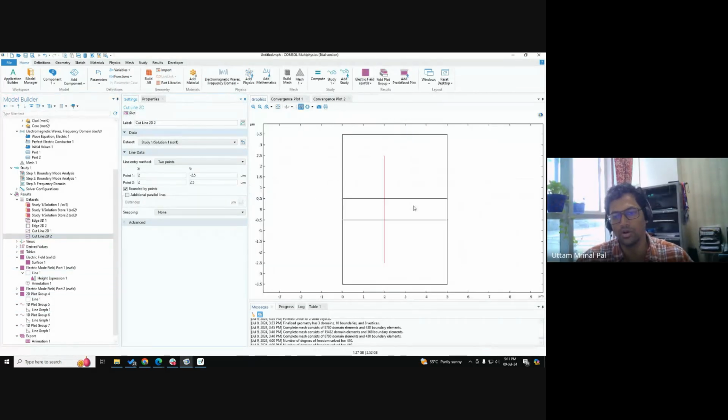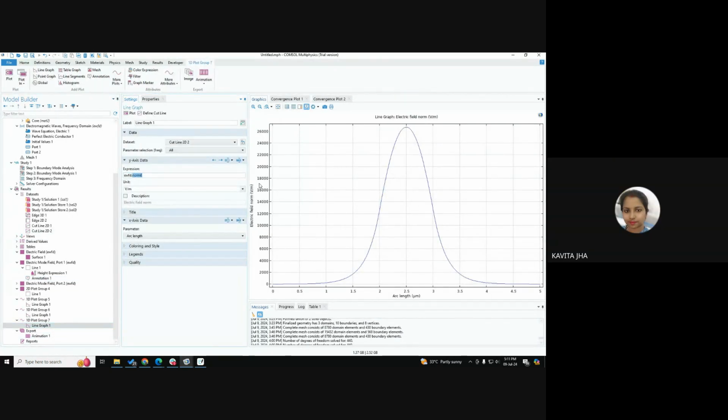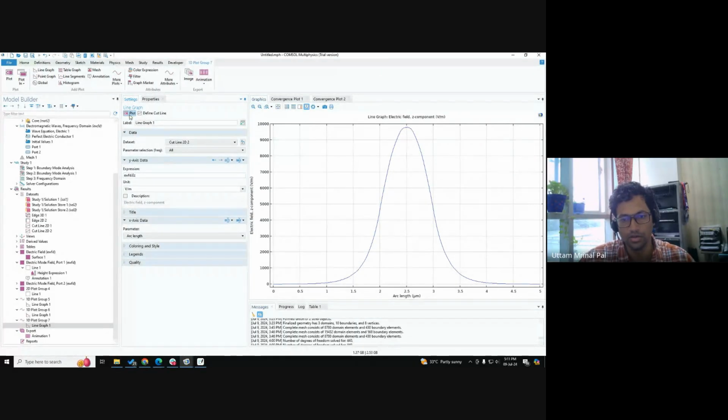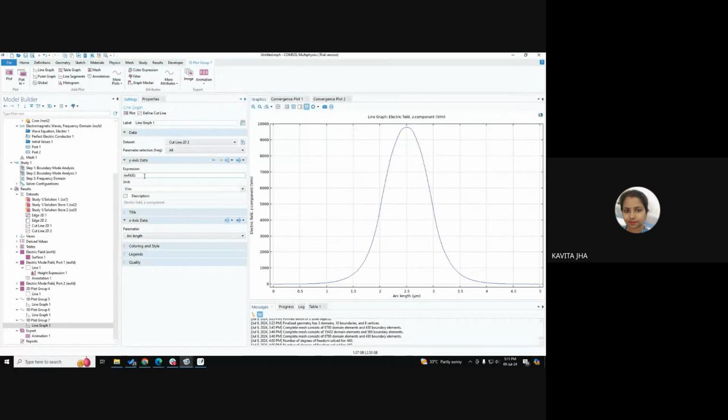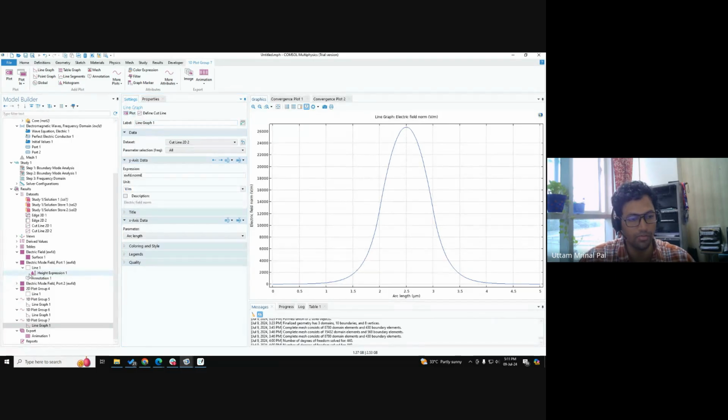So you need to do a transverse cut. What you have done was a longitudinal cut. So you see that it's fluctuating, right? And this I can do at any distance. Unless you're plotting this norm E, if you plot Ez, it becomes based on the phase, whatever phase you're talking about. If you put the norm E, then it is irrespective of the phase. You understand what phase I'm talking about?